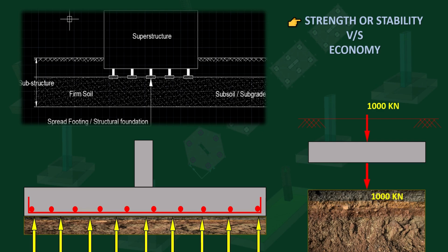But due to lack of knowledge, lack of confidence, lack of awareness, some beginners or practitioners are going to make this design such that they should carry the superstructure load. Yes, they are right, but what they are doing is unnecessarily providing more reinforcement for the safety concern. They are providing unnecessarily more section size. They are going to provide unnecessarily more depth of the foundation to have the strength, to have sufficient stability. And they are not going to consider the other part, that is the economy. Unnecessarily they provide more section size and more depth of the foundation, and it is going to become uneconomical.